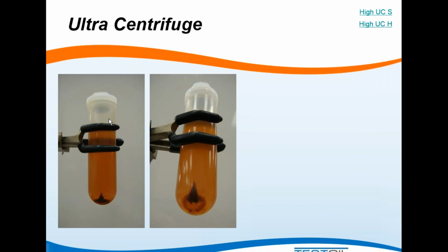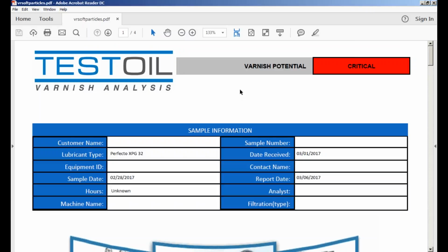And this is what it looks like on your screen right now. So this one scored pretty good. As you can see, there's quite a bit of debris at the bottom of this, and let's take a look at some reports that have issues. We've looked at a lot of turbine reports, but now that we are running into tests that are specific to varnish, we're going to look at those.